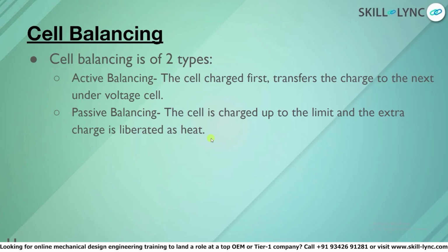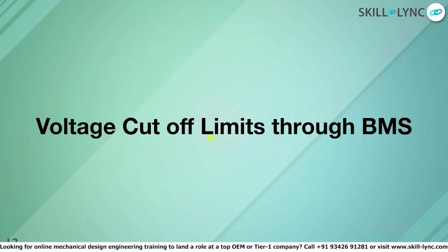At the same time, the circuitry of passive balancing is quite simple, and it is the most widely used balancing technique. It is very economical when compared to active balancing, and the power consumption is also moderately less when compared to active balancing.